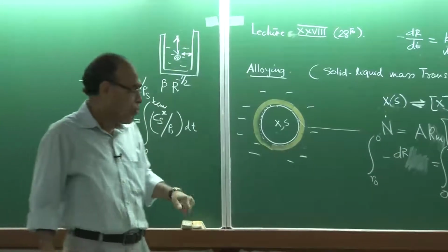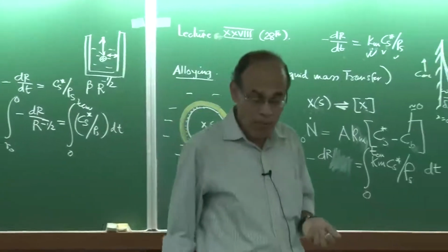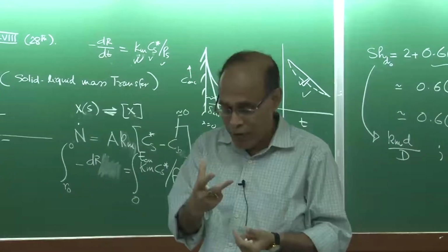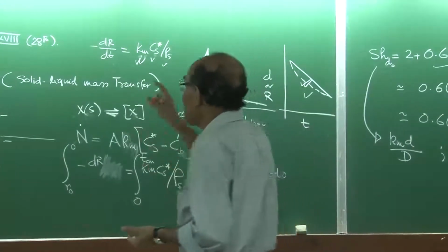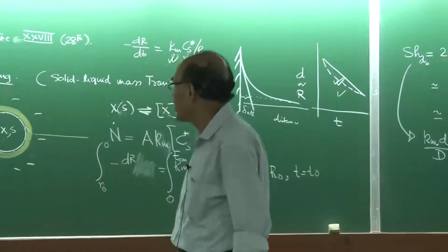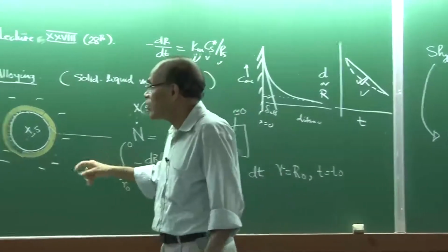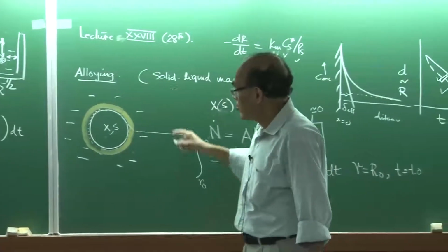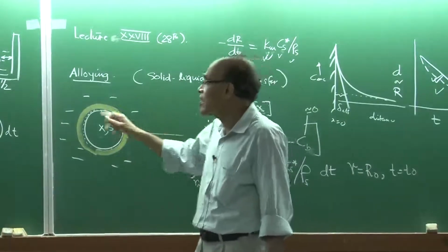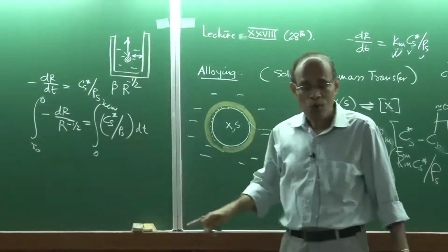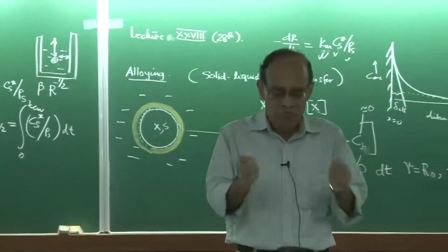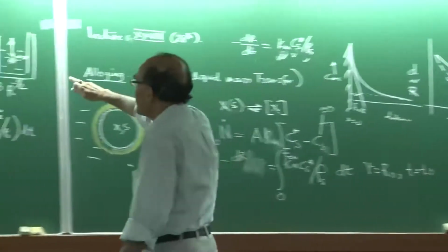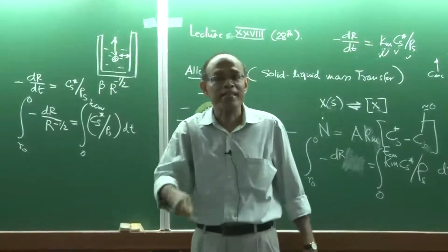So a priori simple design calculations can be performed to tell one what is the optimum level of stirring, and what is the optimum size of the particle that can be added, within the given time, such that one can result in complete dissolution. I would just like to mention that the complete dissolution time of alloying additions is typically much longer than the mixing rates, because in the bulk of the liquid there is going to be an enormous amount of turbulence present in the system.